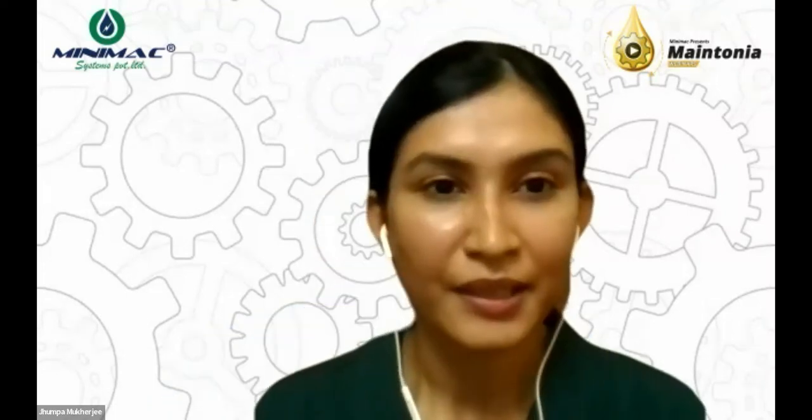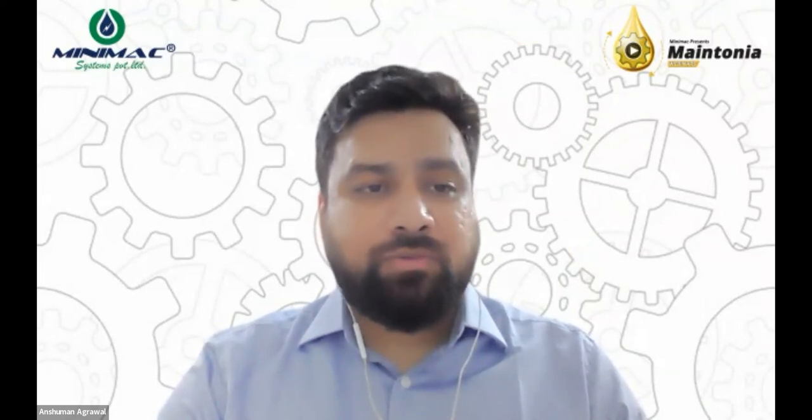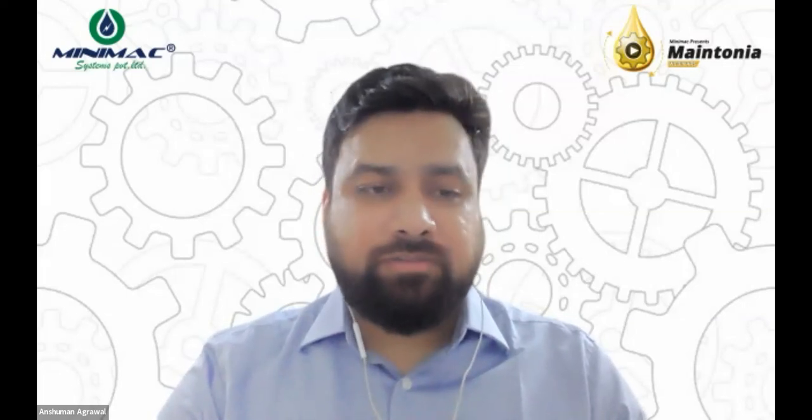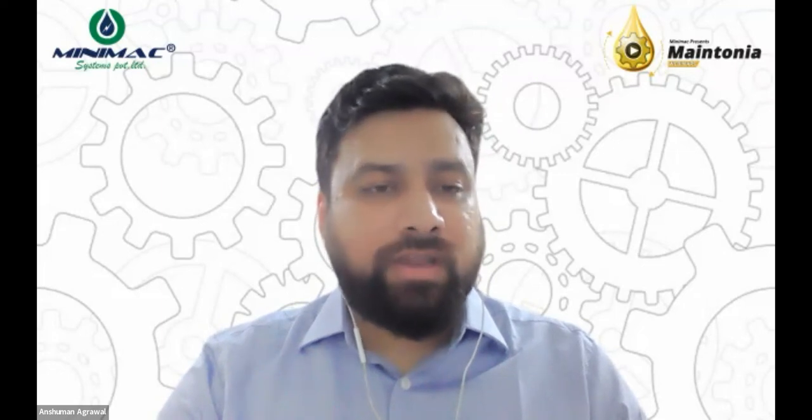Okay, great. So the next question is, please advise us how to select the right moisture separation technique: gravity, centrifuge, coalescing, absorbent, vacuum, depending upon the application, criticality, and equipment. I would suggest whenever it is based on application, it means what type of moisture or water is going to enter your system. So as I mentioned earlier, if it is free water, trust me, centrifuges and coalescer systems, these are the best known technologies.